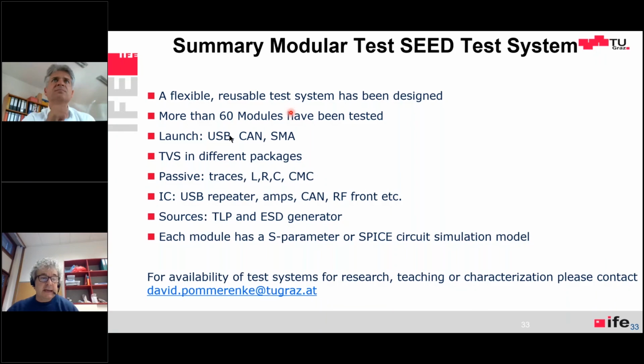What's the range you define as high speed? Well, USB 2.0 I would not consider high speed, but anything where, let's say, the bandwidth is above 1 gigahertz, but in 10 years, the definition would be different. But I say if you need 1 gigahertz bandwidth, I would call it high speed. There are systems which run on 100 gigabit now, and that's certainly high speed. But 20 years ago, the definition of high speed was kind of different. It's a moving target.